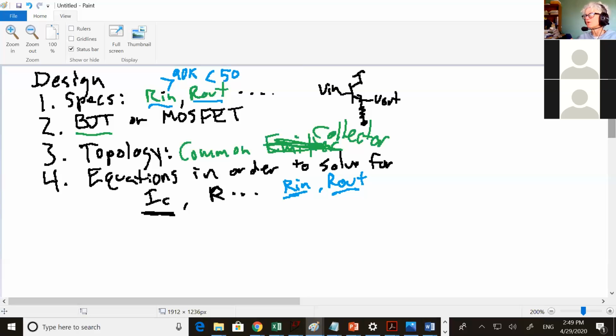So even if I get a weird circuit, it's okay that it looks like a weird circuit. I don't know if that answered your question, but yeah, you get some very odd looking circuits, and if you zeroed the right things, that is actually what it's supposed to look like. Okay. So be expecting an R out value even though we're grounding the input signal. Yes, the dependent current source can still force current through your circuit, even if you have grounds on both ends of it, which is usually where the true weird looking things happen.